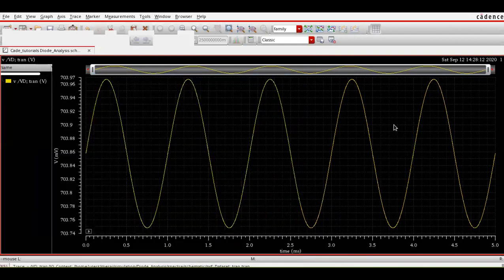So using a simulator is good, but you should know how things are working and what parameters you need to set. Otherwise, you may get wrong results just because your settings are not correct. In the previous sine wave, if you see, there are a lot of harmonics because it was not a pure sine wave. And this yellow sinusoidal signal is much purer than the others.